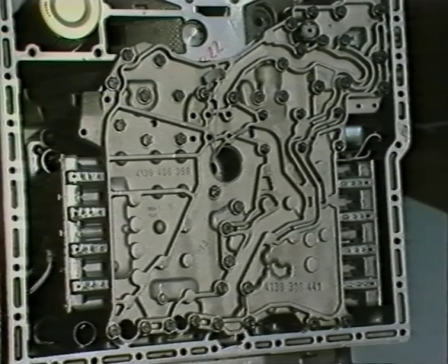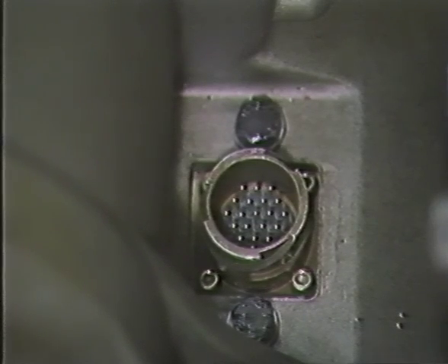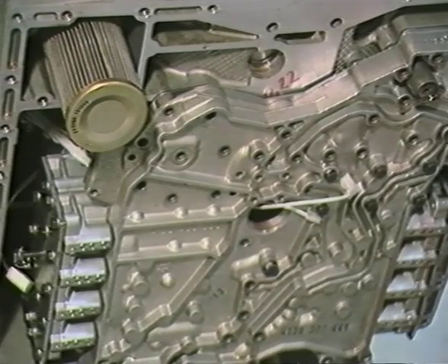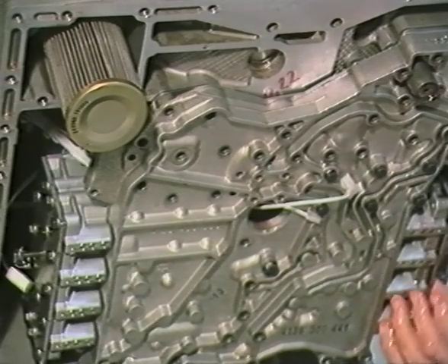Should you require to replace a gear solenoid, this valve block must be removed. To do this, first remove the harness plug by releasing these two screws. Next, disconnect the output turbine sensor wiring. Remove all the retaining set screws, with the exception of these 6 smaller screws. The shift valve block can then be removed.